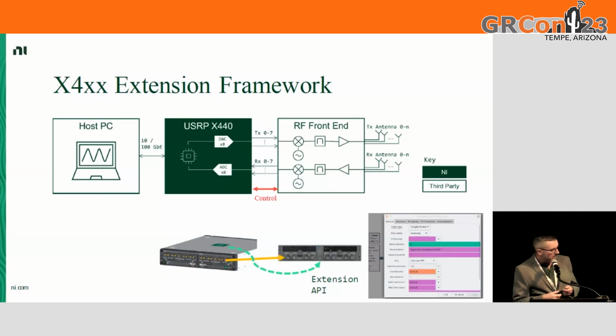I don't know if you can read this from behind, but in this GNU Radio dialog here, we add a device argument that says extension equals SC2430, and that'll prompt UHD to go find a binary plugin that it then loads. If the RF front end changes the available frequency range or gain range, then the device will report whatever that frequency or gain range is.